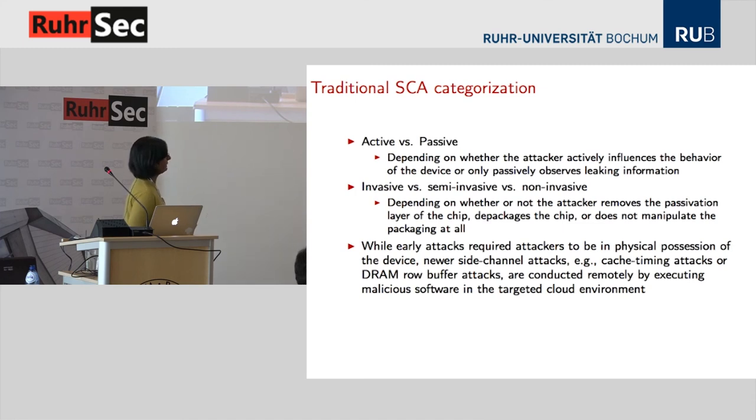So for example, removing the passivation layer of the chip would be considered invasive. Depackaging only the chip is semi-invasive. If you're not manipulating the chip at all, it's non-invasive. So these attacks required the attacker to be in physical possession of the device, but nowadays,